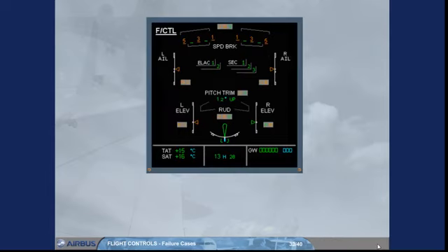As each spoiler has a single hydraulic actuator, when this hydraulic supply is lost, the related affected spoiler remains at its current deflection, unless pushed down by aerodynamic forces.